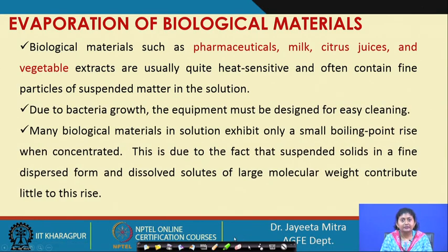During evaporation sometimes those materials can be deposited on the surface of the liquid side, and if they are not cleaned properly then bacterial growth can occur and the contamination will be high. So, the evaporator should be designed in such a way that proper cleaning can be done.